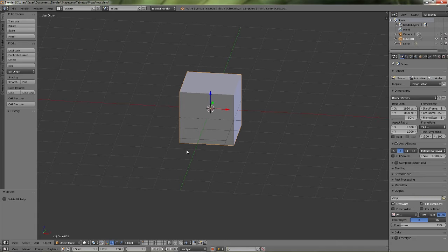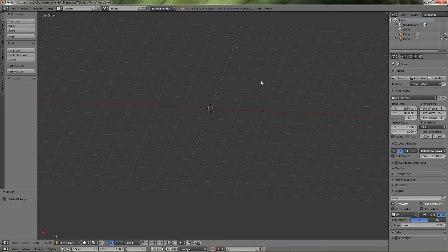Awesome. So to get started, you'll notice that I'm in object mode. There are quite a few other modes that you can use as well, but we're only going to worry about edit mode and object mode. So first, let's model a vase, because that's something very simple and easy for you guys to follow along with as one of your first models. Obviously a vase is going to be round unless you're doing something cooler and maybe modern, but I'm going to do a round vase. So I'm going to delete this cube, hit X, enter, awesome, it's gone.